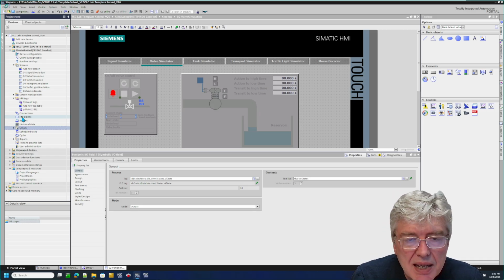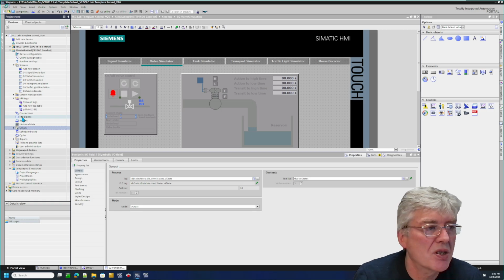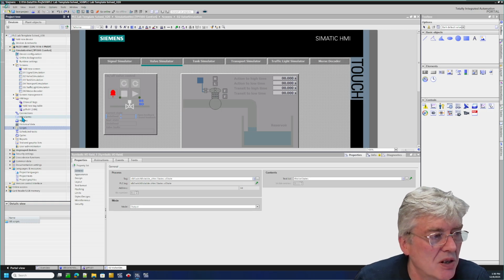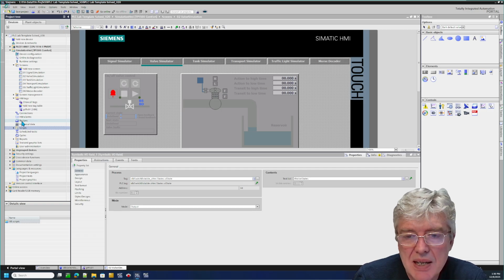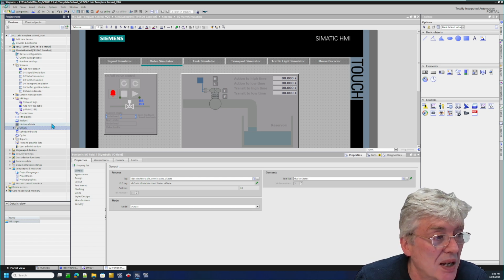Then there are the alarms, where you get a list of exceptions or alarms that you have. They are not really especially good with these Siemens panels. And recipes is where you have recipes that you can load down to the PLC for mixing paint or whatever. So they are recipes. Historical data, the data that you store. Cycles you can define. That's for the tags, how often you want to have those.